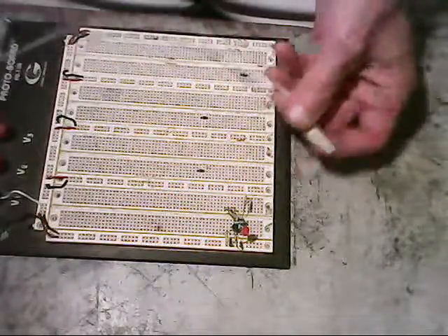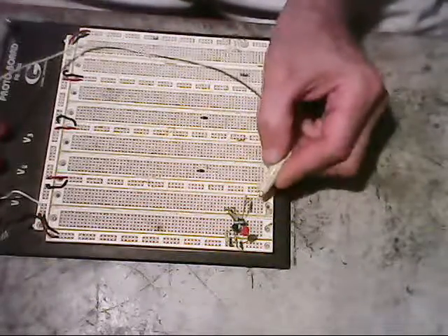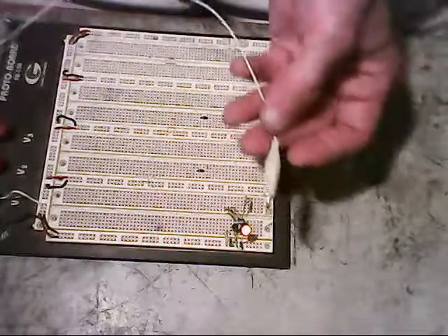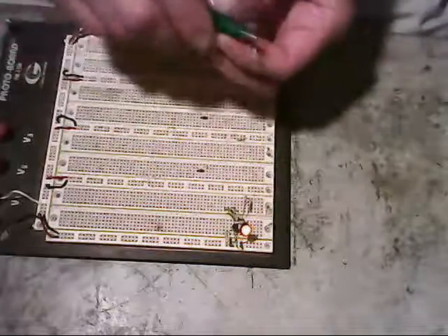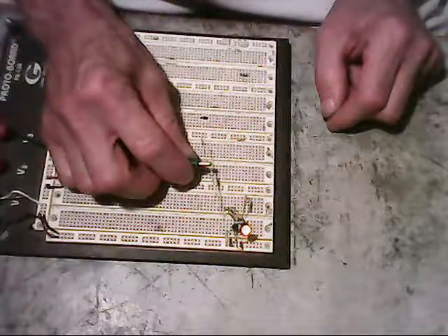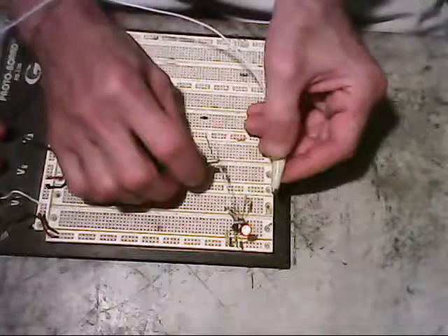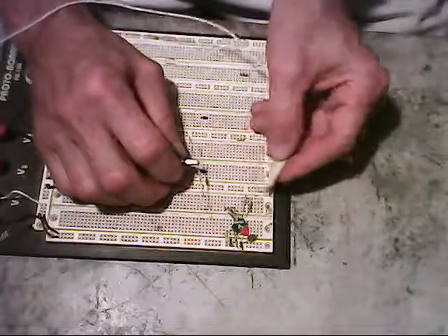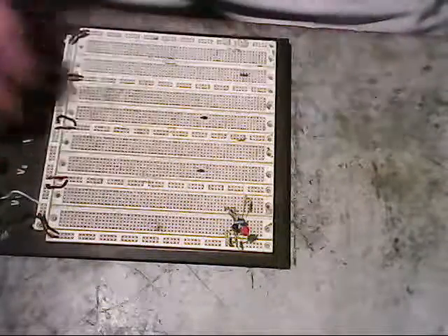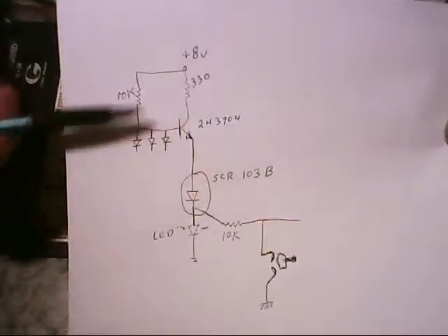I'm going to use this white wire connected to the positive side of the battery to touch on to here. And when I touch this, the light should go on and stay on when I take the input off. Now this wire here is connected to the negative side of the battery, and if I touch any one of these diodes, the SCR is off again. So through every one of the 3 diodes: first diode, second diode, and the third diode. So what we have accomplished is a way that we can turn the SCR on and turn the SCR off.